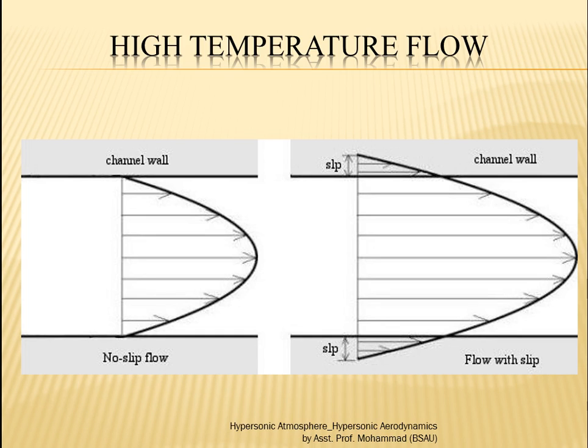At that time, kinetic theory must be used to predict the aerodynamic behavior of the flow. Finally, the air density can become so low that only a few molecules impact the surface per unit time, and after reflection they never collide with the incoming molecules. Such a regime is called free molecule flow.